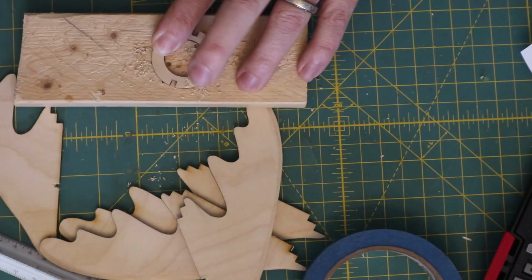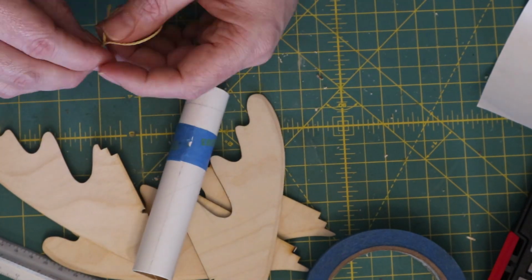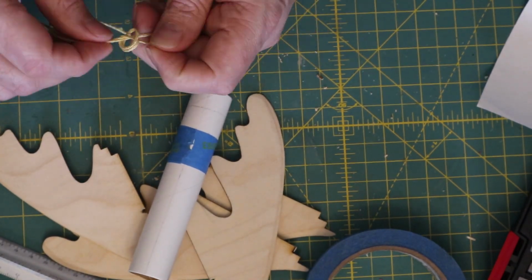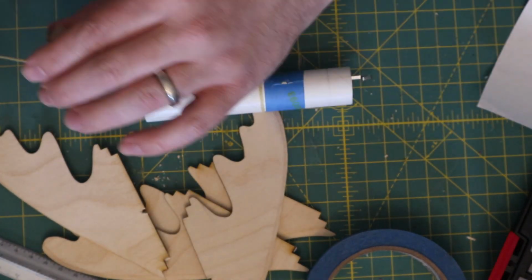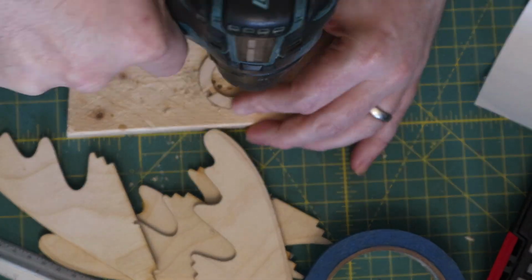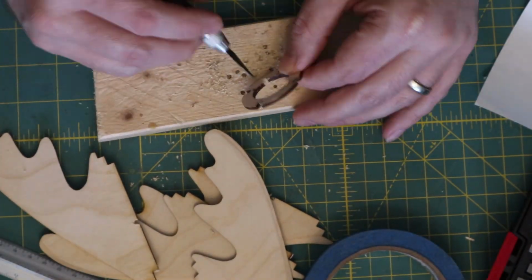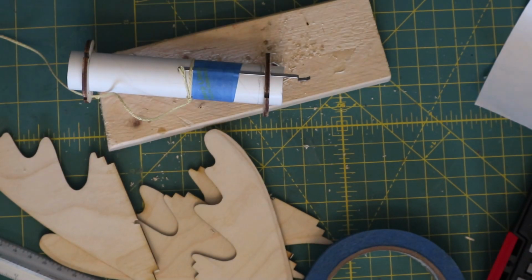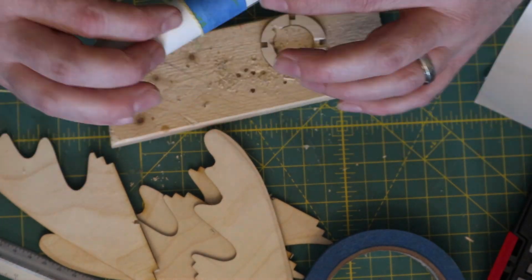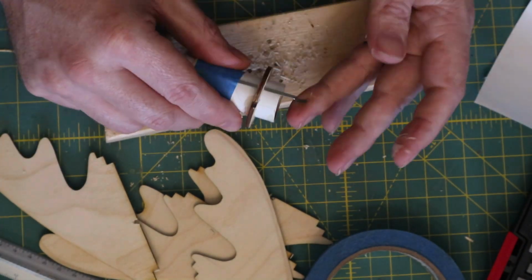And we did want to place this down where the motor will be, just because that'll provide a lot of structural reinforcement as well. Now we're going to add a notch to the bottom centering ring just so that there can be a little travel on that motor clip. Clean that up and then put that on. Once we're happy with that, we're going to make sure that, of course, they line up, and then we're going